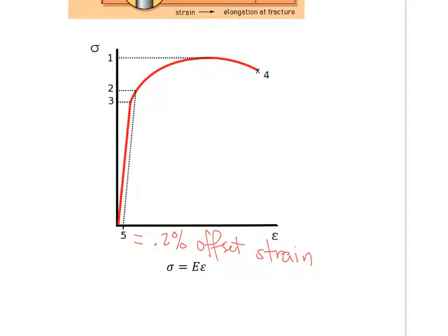And what this means is you can go to about 0.2% strain, which is really, really small. If you had a specimen that was 100 centimeters, think about 100 centimeters, that's a meter, if you had a specimen that long, 0.2%, that's 0.2 centimeters, it's very small, 2 millimeters of stretch. So under this much stretch, if you take a line parallel to the motion of the stress-strain curve and see where it intersects at 0.2 up there.